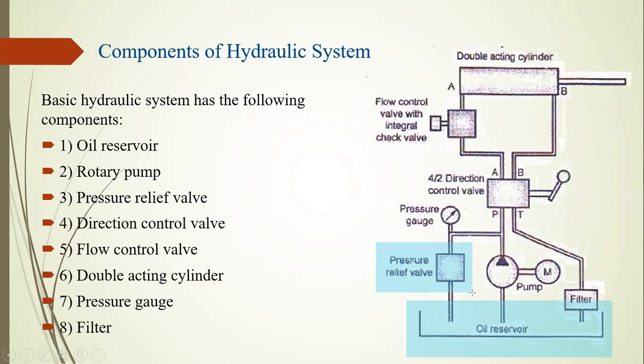When the pressure becomes high in a hydraulic line, what happens at this time? It creates a critical pressure inside the line. Whenever the pressure is critical inside the line, it can cause damage, leakage, or an accident. So, to balance the system completely, we always attach one pressure relief valve so that the high pressure can be relieved in the pressure relief valve and the system can balance.